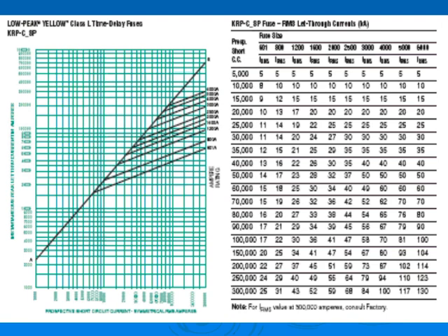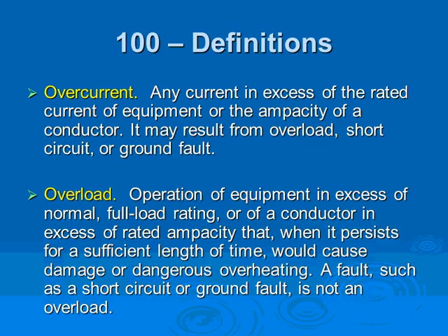So this is just emphasizing the idea of a short circuit. Current limiting fuses, are you guys familiar with current limiting fuses? When you have a current limiting fuse, when it operates within its operating limit, it will knock down the current, the instantaneous, as well as the RMS value. I do have a couple of examples later on of how current limiting fuses will work. Current limiting fuses are awesome in terms of knocking down the arc flash energy and the blast that's coming out of the system. We'll talk about them later on.